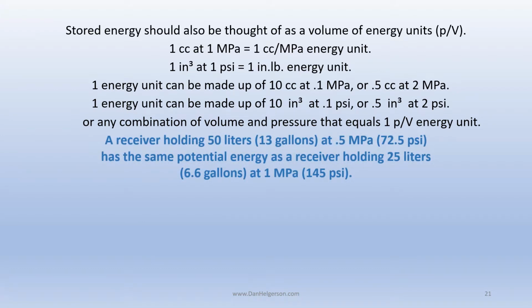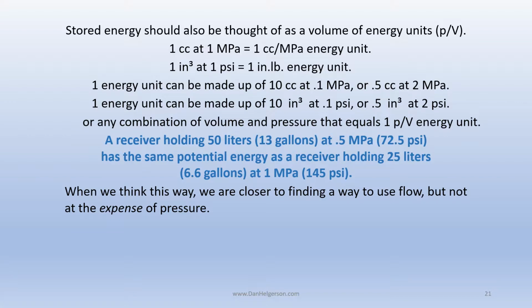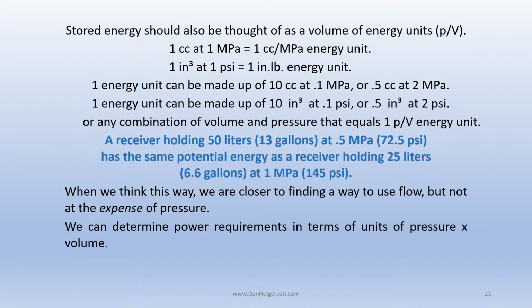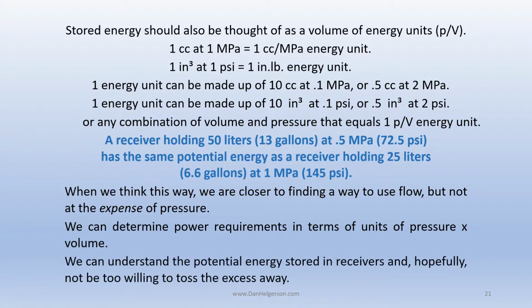A receiver holding 50 liters at 0.5 megapascals has the same potential energy as a receiver holding 25 liters at 1 megapascal. When we think this way, we are closer to finding a way to use flow, but not at the expense of pressure. We can determine power requirements in terms of units of pressure times volume. We can understand the potential energy stored in receivers and hopefully not be too willing to toss the excess away.